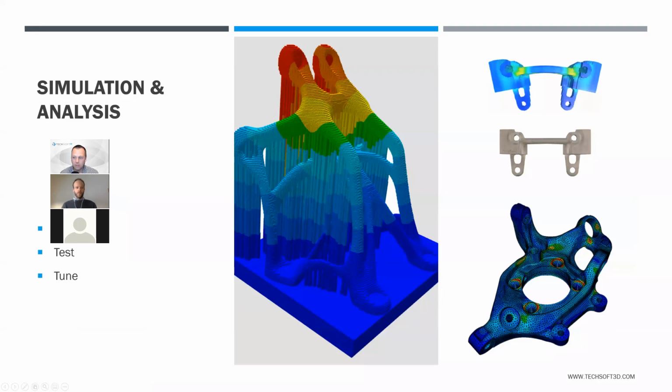And then the last part we want to talk about is relatively new to additive manufacturing. Many times we were just happy to print, and if it worked, that's great. If it crumbled, well, we'll go back to the drawing board and redesign it. Some of the first things we did were figure out what's the percentage of shrinkage when we manufacture a part. But now we're seeing within that workflow a whole step or suite of analysis tools that allow you to say, how does this behave under heat? How does it behave under pressure? What's our thin wall thickness right now, and does it need to be changed?